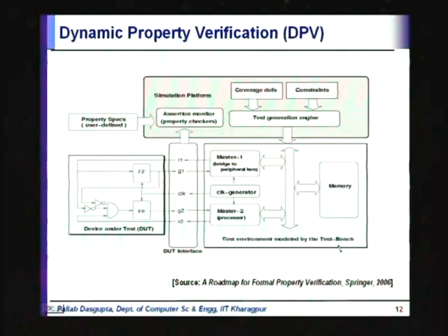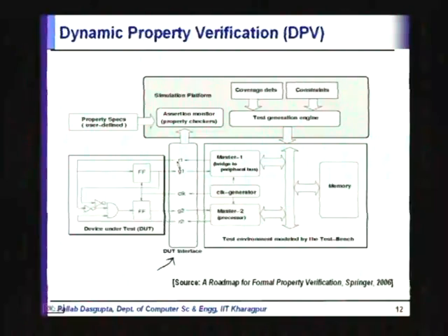Okay. Now, in these modern languages we have the concept of an interface, which is one of the new things that came up when we had system verilog developed out of verilog. What this interface does is that you can define that these are the variables in the interface, and you can bind the interface to this side as well as this side.